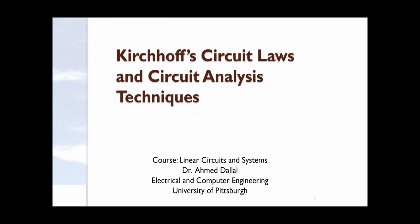Hello everyone. In this video, we review Kirchhoff's circuit laws, namely KCL and KVL. We also review how to convert a KCL equation and represent it in terms of node voltage. Same for KVL, we represent it in terms of mesh current. This leads us to node voltage analysis and mesh current analysis. Both are simple yet effective techniques to solve for circuit parameters.